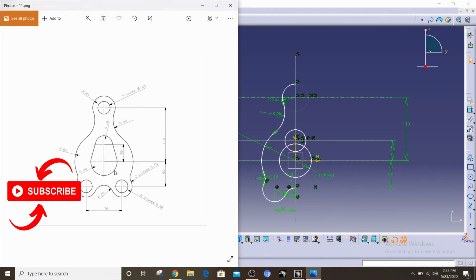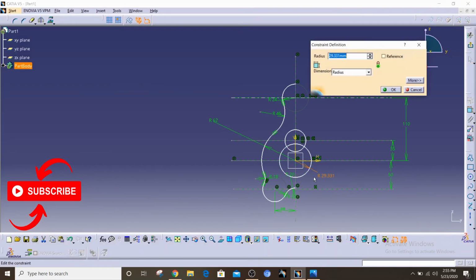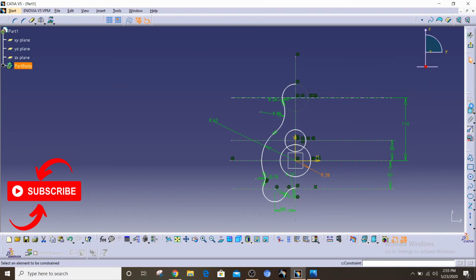So the lower circular arc is 28 units. The upper arc is 18 units. And then we're gonna join them together by using a bitangent line, which is basically a line joining two circles through their tangent. And I'm going to trim off the rest of the thing.